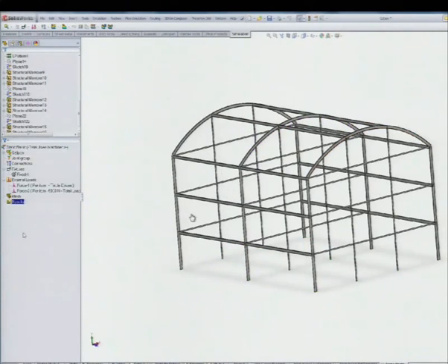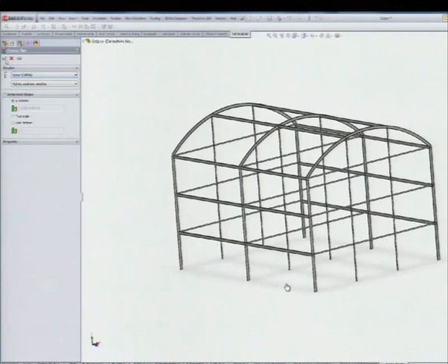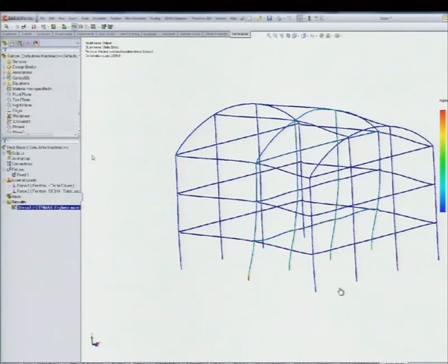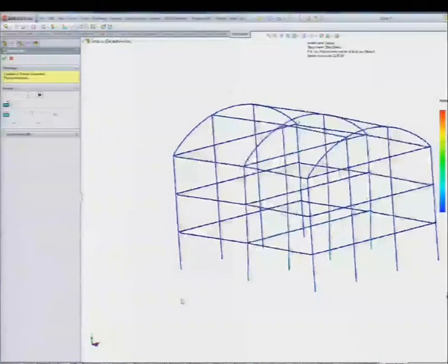and what I get from SolidWorks simulation, first of all, stresses, right? What for? With the stresses, I check the stress of every element, every member of the structure. I compare with the yield stress. If the actual stress is higher than the yield stress, I have an issue, right? I have to make some decision in order to change it and to get it lower. So stresses, this is static, right? This is the very basic analysis. Stresses.